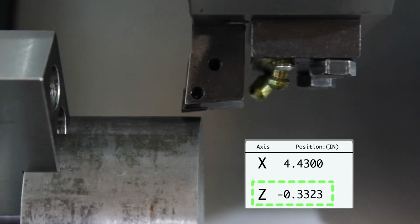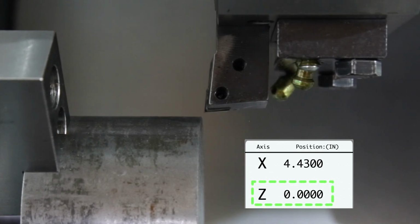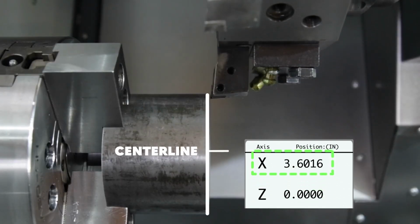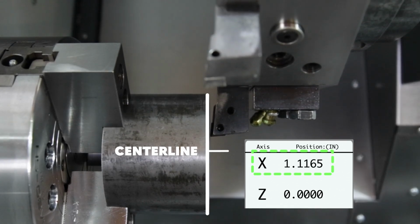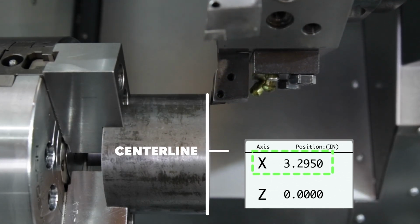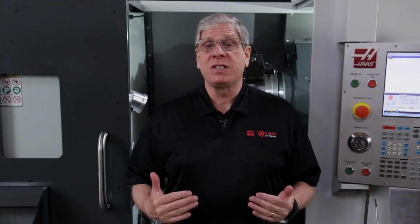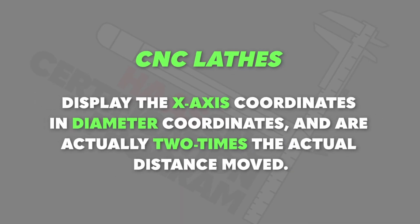And anything in this direction shows us positive. The same is true for the X-axis. The center line of spindle rotation is X0, and as we move away from center line, all the coordinates are positive values. The interesting thing about most CNC lathes is that they display the X-axis coordinates in diameter coordinates and not the actual distance moved along the X-axis. Diameter coordinates are actually 2 times the actual distance moved.